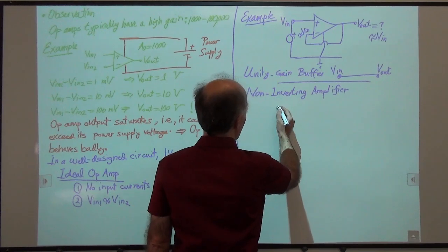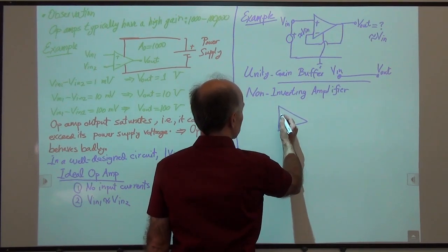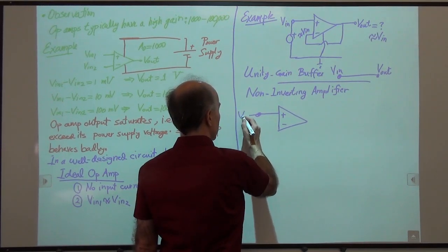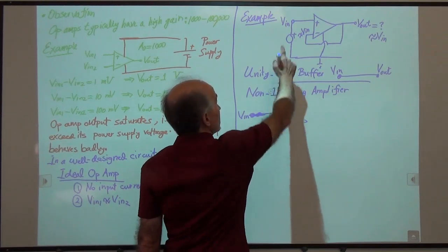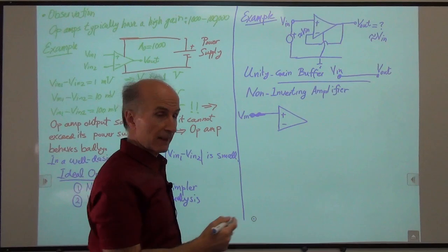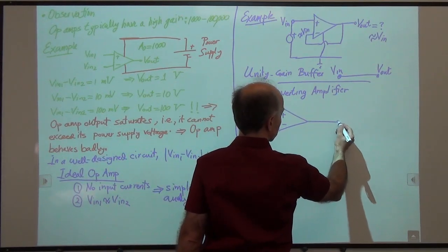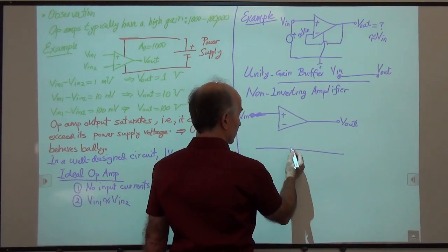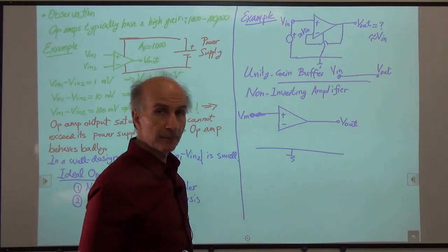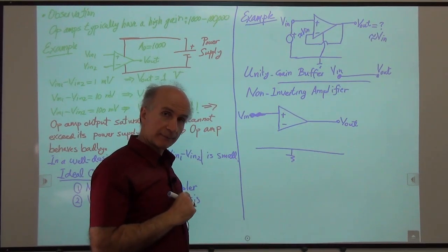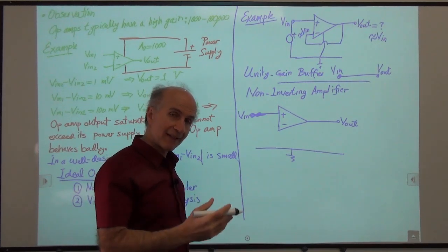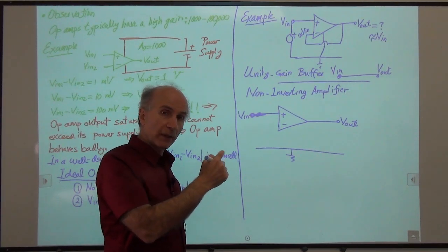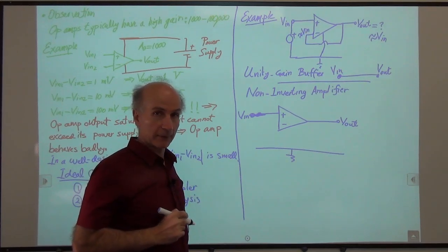All right, so here's how it goes. I have an op-amp, and it's receiving an input. Again, we just call it V in, just like before. There's an output, V out, and we have a ground, right? Everything has a ground as a reference. What we will do is take the output voltage, pass it through a resistive divider, and then return the result to the inverting input of the op-amp.